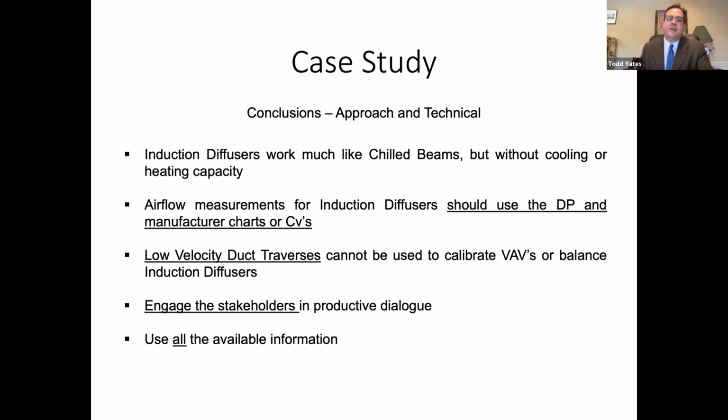Now, in the end, a lot of times we don't even show VAV total in an air handler sheet because of diversity. If you have a 10,000 CFM air handler, but there's 12,000 CFM of connected load, they won't match by definition because they're not simultaneous readings. I'm not sure which question you're answering, or asking, but hopefully I answered at least one of them correctly.